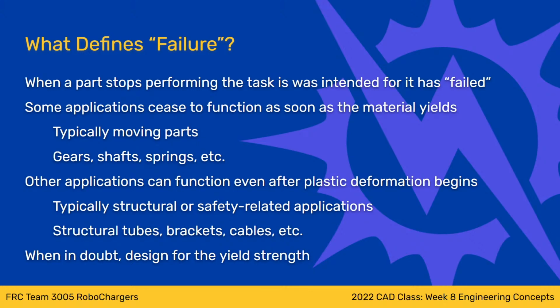And as soon as that shaft gets a little bit of a bend to it, it can bind up and it won't work. It can't move anymore. It's gone. Things like springs. Springs are very, very specifically tuned to operate in their elastic region and not undergo any plastic deformation. And as soon as they undergo plastic deformation, they don't have as much spring force, or the spring rate is different, or whatever it is, depending on how it bends. It's pretty much useless at that point.